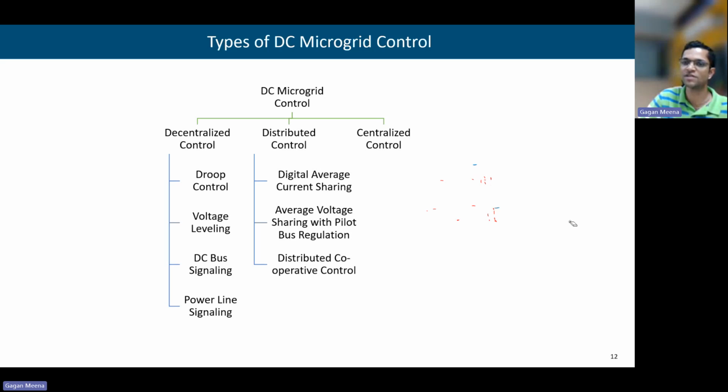There is poor load sharing when there is good voltage regulation, and poor voltage regulation for good load sharing. Also, for a small group, there is less voltage deviation between the converters, but for a large group, it leads to a larger difference in current sharing.